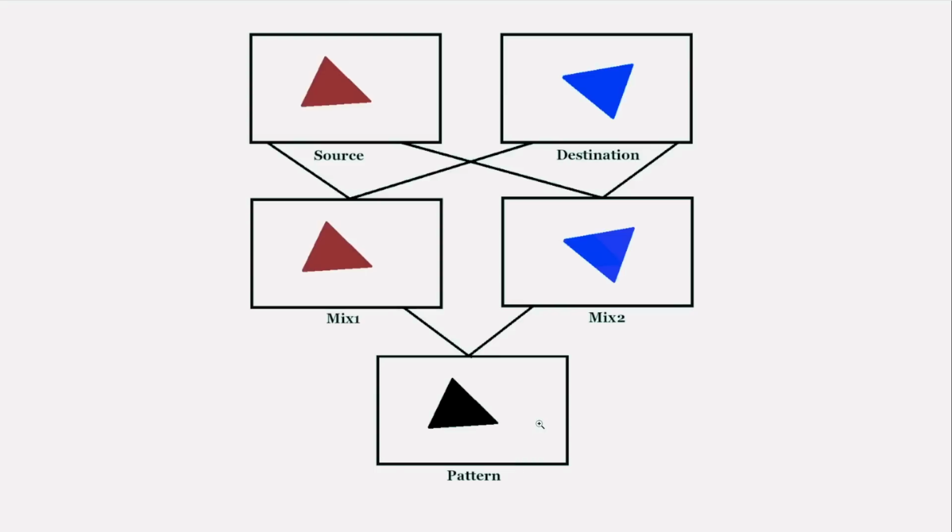On the 8514/A, there were only certain places the pattern information could come from. One possibility was to take it from system RAM, in other words, you'd supply the pattern yourself, and it could be arbitrary, anything you wanted. Another possibility was to use a repeating pattern of just a couple of bytes. You'd put those into some special registers in the coprocessor, and then they would just be repeated over and over again for the pattern information. Now that'd be useful if you wanted to fade one image into another image. Basically you just add more and more black pixels to your pattern information, and it would just take more and more pixels from the first mix instead of the second mix.